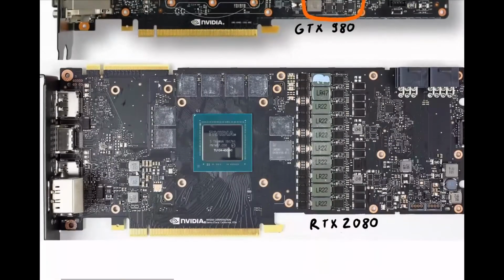And then on this RTX 2080, you have one big strip of VRM. You can actually see which is vMem and which is vCore from the inductors, because they have different inductance values. So this one right here has 22 and this one has 47 as its inductance value, which tells you that it is used for a different VRM. So yeah, that's how you can find out.